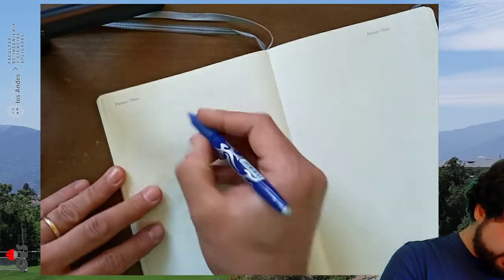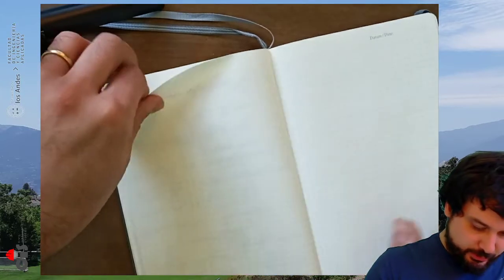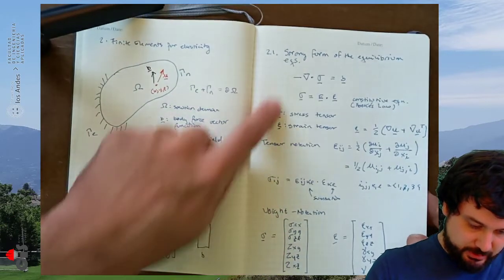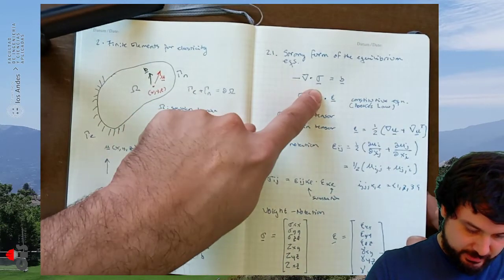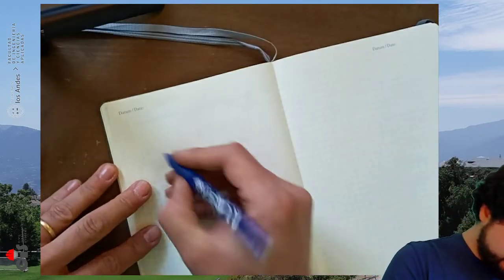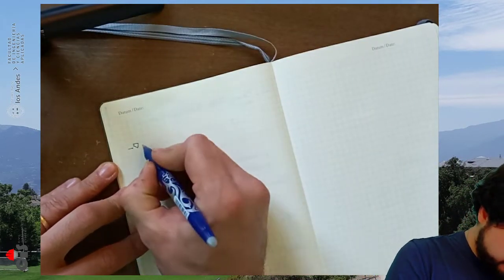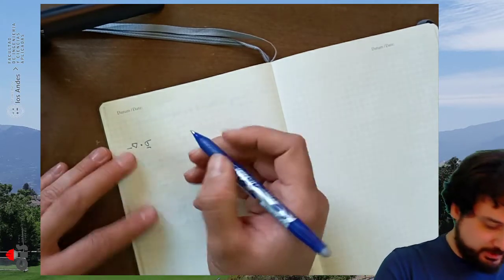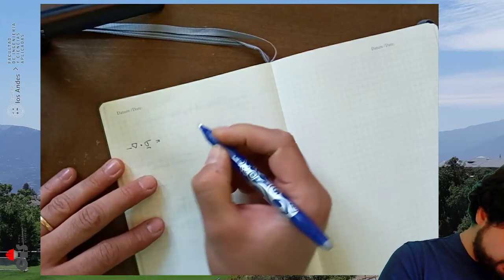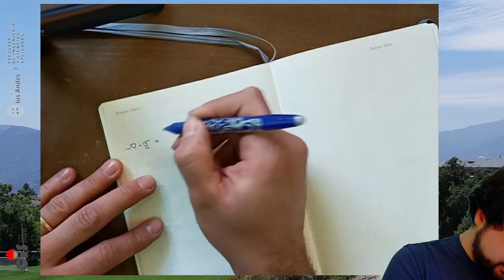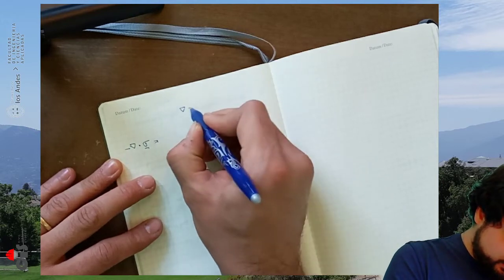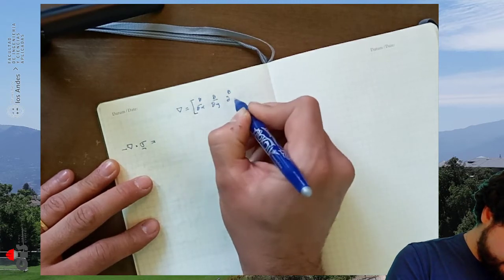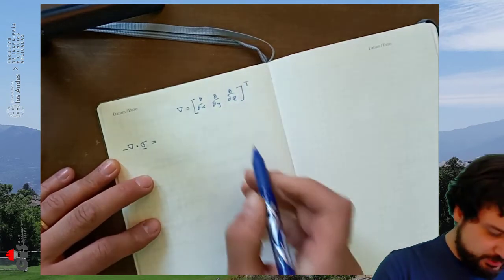So in Voigt notation, we want to write this divergence operator. It's going to act on the tensor. The way that looks is nabla sigma. This gives you a vector, because the right hand side is a vector, right? So it's equal to the b's. But here, this nabla is always going to be d dx, d dy, d dz, transposed.